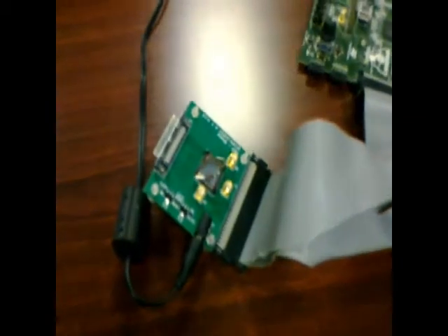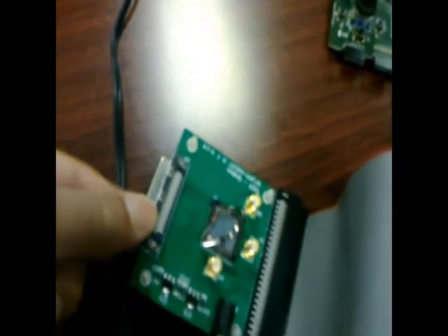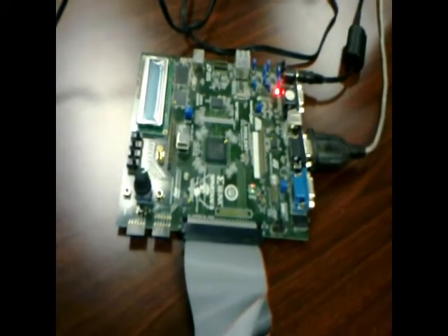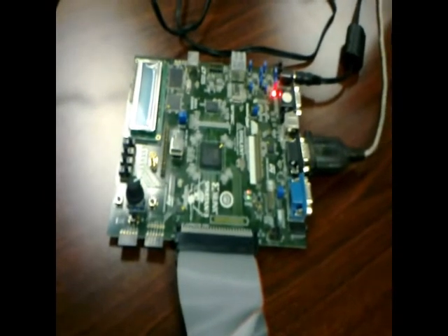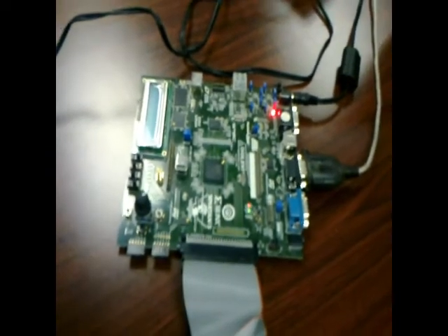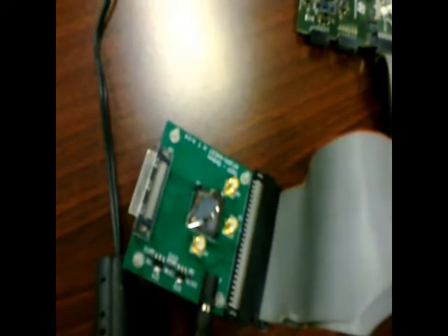Now we will see a live demo of our test and characterization platform. This is our prototype chip inserted on the socket here in the test board, which has 2 interfaces to 2 popular FPGA boards actually. Through this interface it is connected to an FPGA board that contains a prototype of the test processor. This is a very low-cost FPGA board. It's connected to the user PC through a serial port or serial communication. In the future, we plan to place the test processor as an ASIC here on the same test board with the chip being tested.